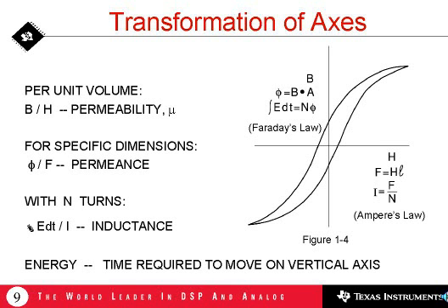But it is constrained only indirectly, because if we have an inductor made of this core material, we are constrained to follow that characteristic. And we are also constrained on the vertical axis by time, as shown, integral volt-seconds. This means that indirectly we are also constrained on the horizontal axis as well. But if we imagine a characteristic which is horizontal, we can traverse that characteristic instantaneously because no vertical motion would be involved.